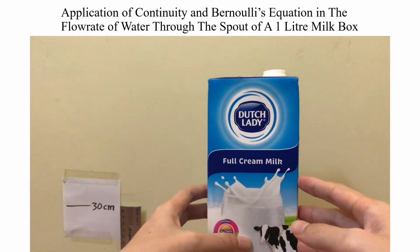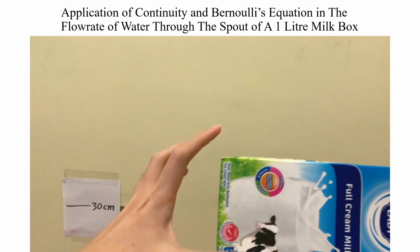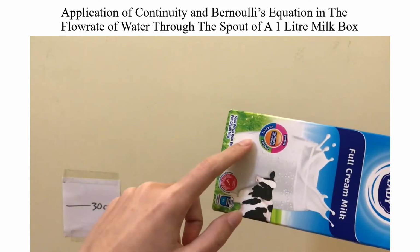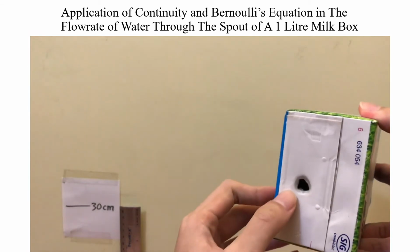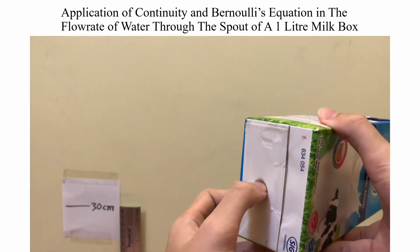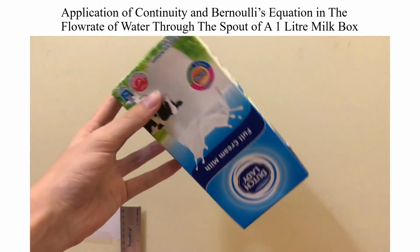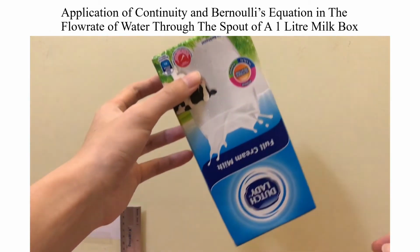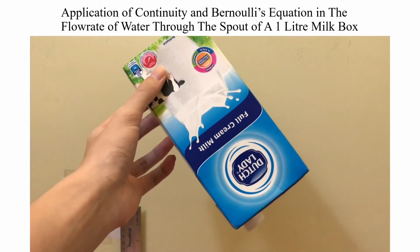So what we've done is to actually balance the pressure in the box and also with the surrounding. And in order to do that, we have actually punctured a hole at the bottom of the box to ensure that when fluid is being poured out, there is no disruption in flow due to the difference in air pressure.